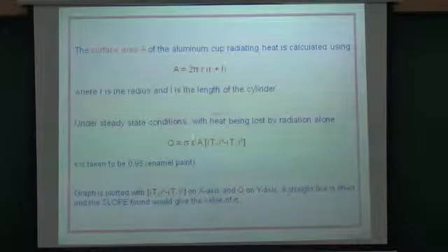We have to wait till the thermo EMF shown by the DMM reaches a steady value. It is about 1 hour, but you have to wait for 40-45 minutes till this becomes constant. Then we reverse the terminal on the DC differential amplifier to find out the negative values also. After this, we reduce the current in steps of 20 milliampere till 100. So we start from 200, 180, 160, 140, 120 and 100.